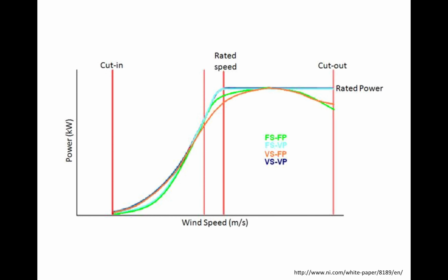So if we want to reduce, for example, the rotational speed of the blades, we cannot increase the back torque, which is the electrical torque from the generator. We cannot do that because the generator is already running at its maximum capacity. Increasing the electrical torque will just burn the generator. So electrical means is not available to us anymore, even if we have a variable speed wind turbine.